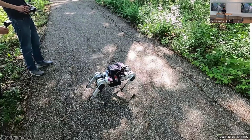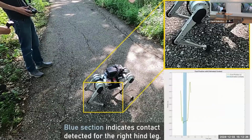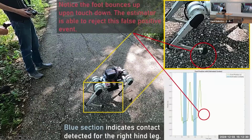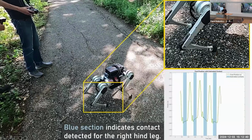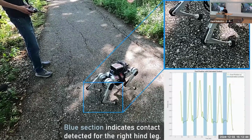This is a qualitative result of foot contact estimation. You can see that when the robot first makes contact with the ground, its foot actually bounces up. That is fatal for state estimation because it violates the zero velocity assumption. But our contact estimator can reliably remove that from being estimated as contact.